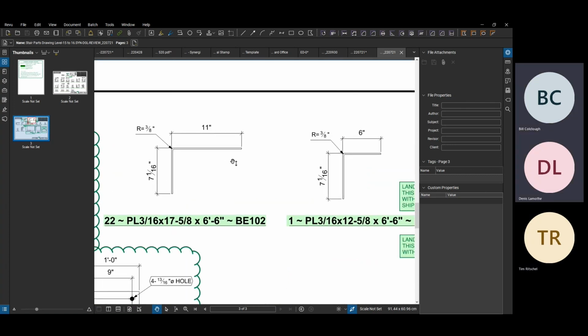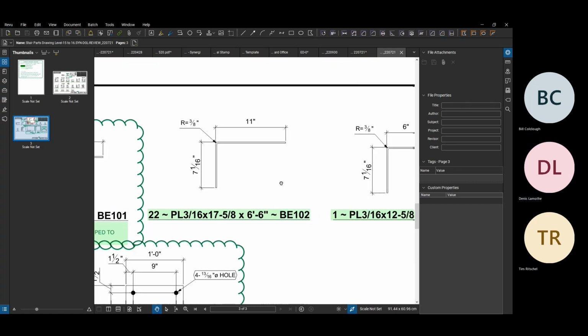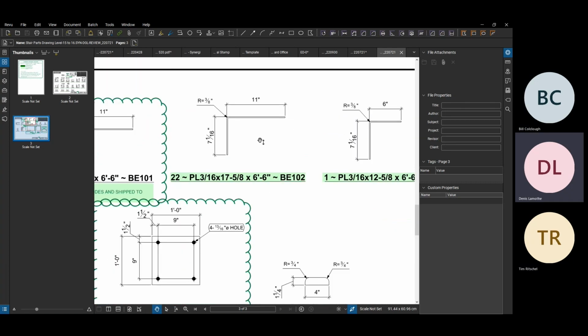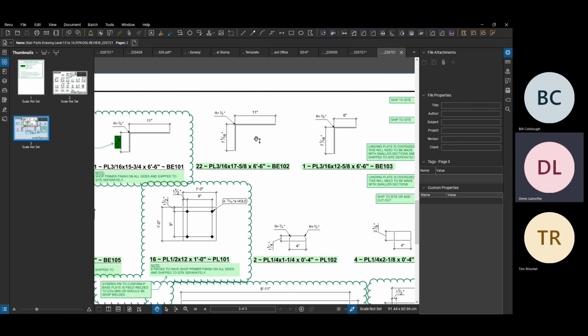We may work on a special project where we are machining parts and we do require that tolerance. If that's the case, I think for the most part we'll be made aware of it, that we're machining this, it's going to be put in a CNC machine, and we need to show the tolerances. At that point, yes, you can make a special override for that one dimensional part so the dimensions show a higher degree of precision. But for bent plate, bar stock, and all that stuff, 16ths of an inch is generally pretty good with us.